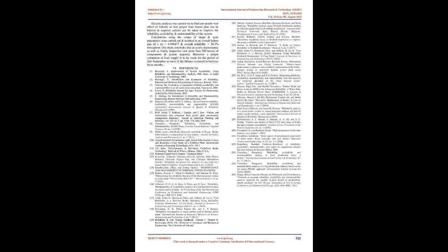This research project was based on applying discrete and continuous lifetime analysis using the Weibull distribution function. The study involves analysis of failure times of a boiler system of a power generation plant using the least square estimation method. The failure times were rank ordered and estimates of the two-parameter Weibull distribution, shape and scale parameters, were determined using software. This method of estimation was found to be very fast and more accurate than the manual approach.